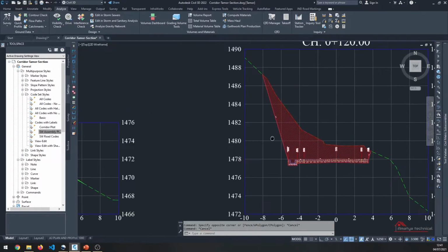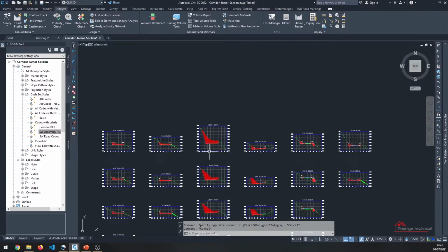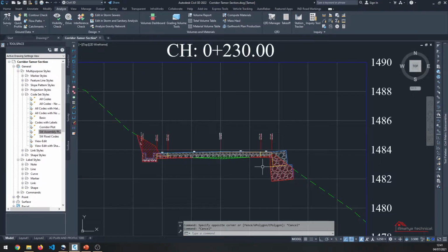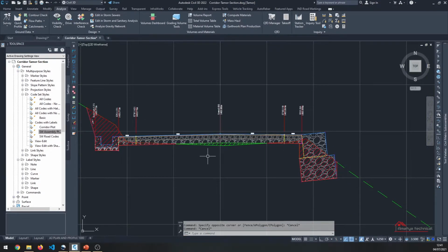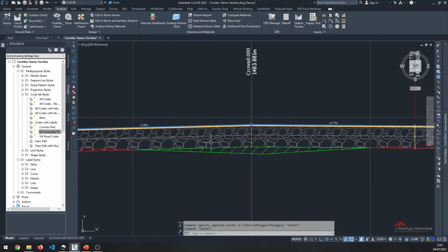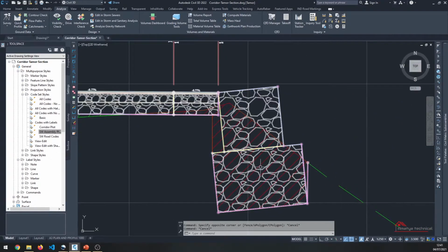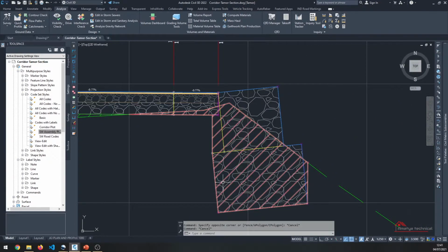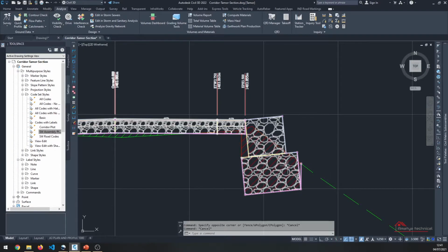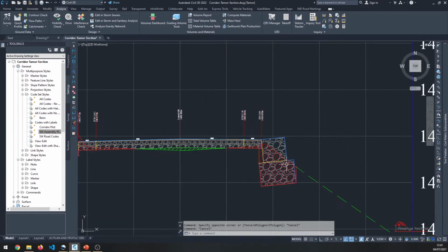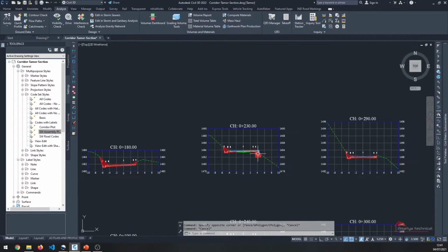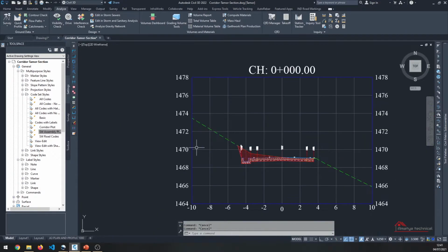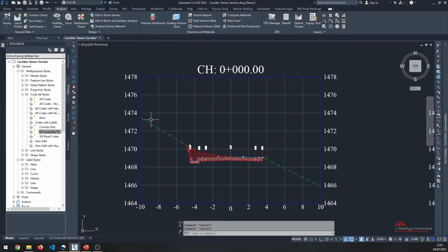Let's go through all these sections. Here you can see this is our cut. So this was I was talking before. This is our artwork or cut for the embankment. This is our fill, and this is our structure code, but this we cannot specify here because we have used the same code for both this section. That's why you can't do anything for that for this assembly.